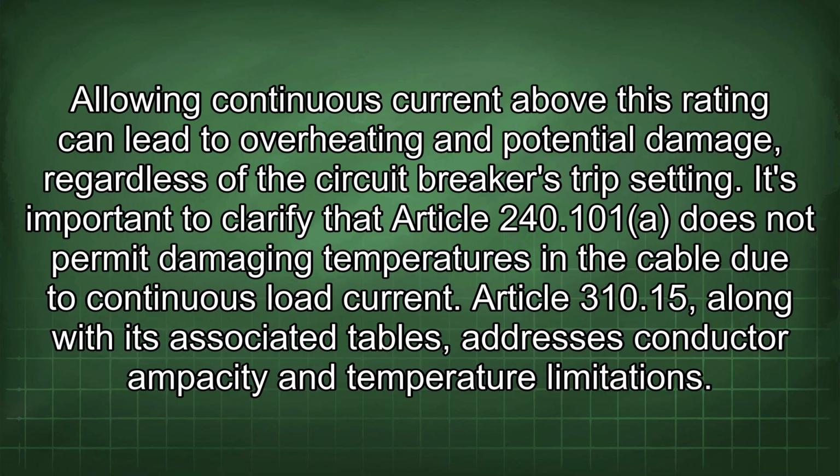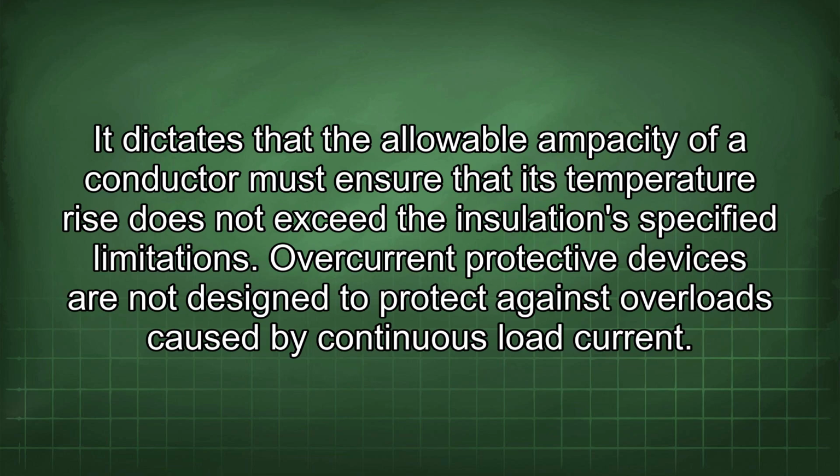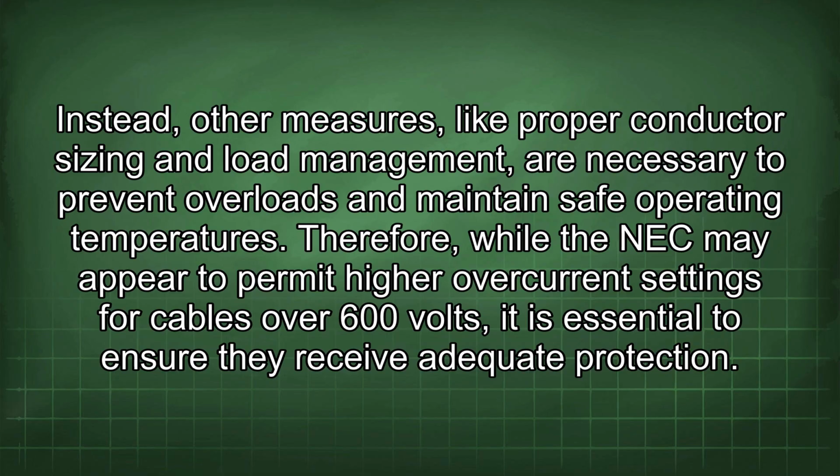Article 310.15, along with its associated tables, addresses conductor ampacity and temperature limitations. It dictates that the allowable ampacity of a conductor must ensure that its temperature rise does not exceed the insulation-specified limitations. Overcurrent protective devices are not designed to protect against overloads caused by continuous load current. Instead, other measures, like proper conductor sizing and load management, are necessary to prevent overloads and maintain safe operating temperatures.